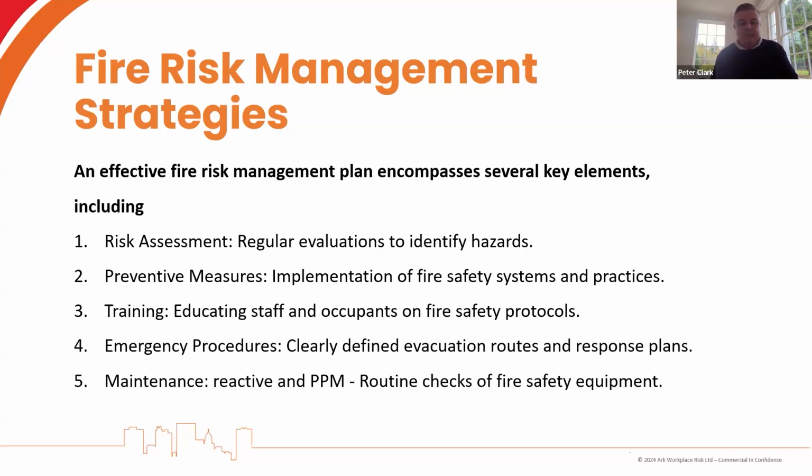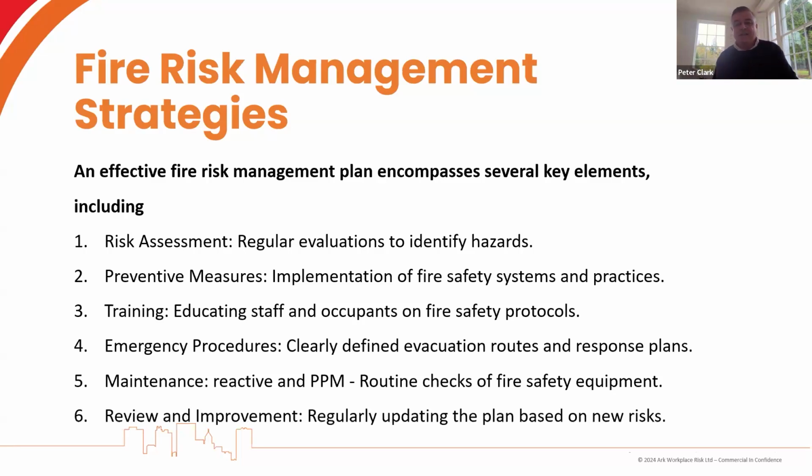Maintenance: reactive plans, preventative maintenance, routine checks of fire safety equipment, all now enshrined in law depending on where you are in the world. The Fire Safety England regulations, for example, will ensure that you're checking these things in the right way and in the right timescales. Review and improvement. Let's never forget that even if we get this right, that's fine, but we need to keep reviewing.